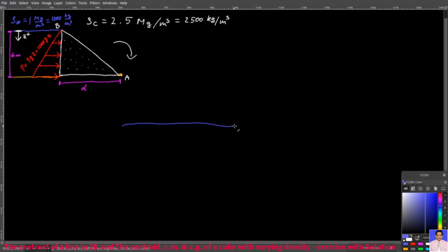So in general, if I have a plate underwater, even if it's at an angle, then if we take this side here, then the pressure would vary linearly with depth, and it would be normal to the surface. In other words, it would be perpendicular to the surface.